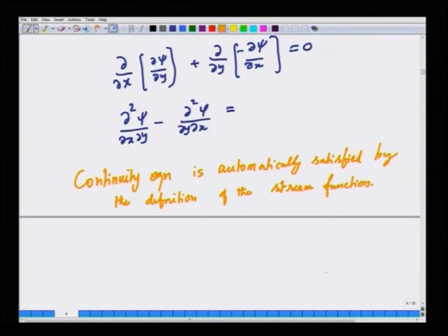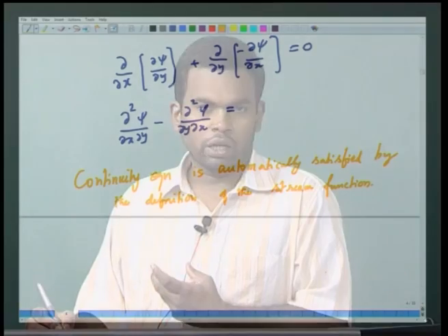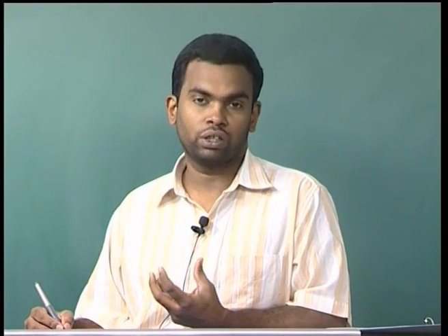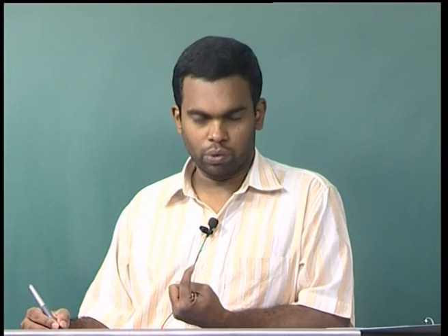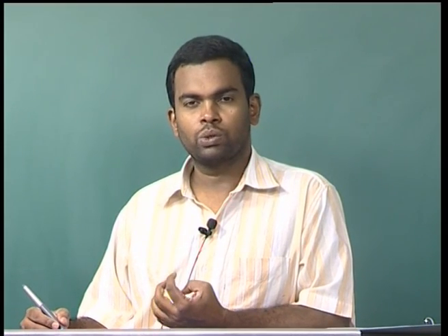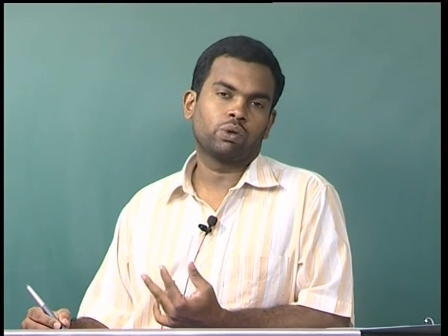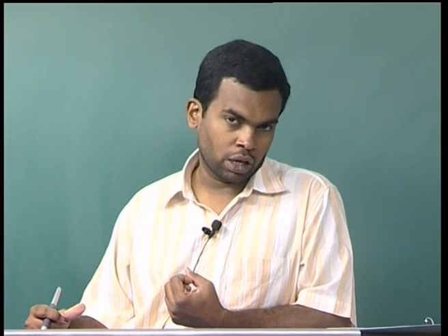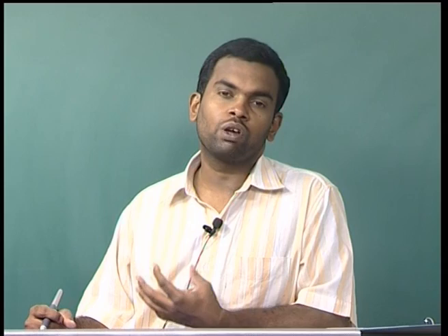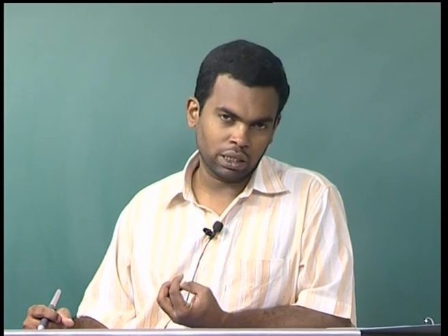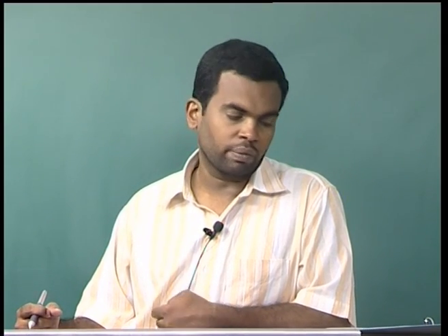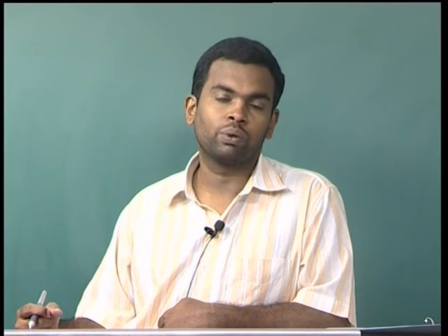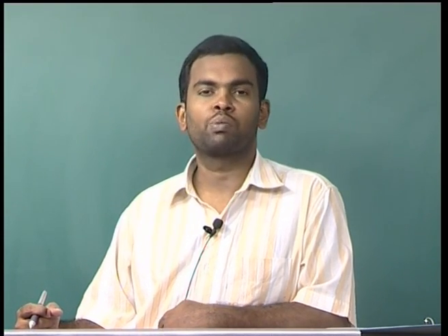So, this is a very important conclusion, because by defining the stream function in this fashion, you are automatically satisfying the continuity equation for 2-dimensional incompressible flows. That is a great simplification, because when you want to proceed further to momentum balance, you will find that you will have two sets of equations, the mass balance and momentum balance, which are coupled to each other. But by defining the stream function, you are doing away with one equation, you have to solve one equation less, and it is always nice to solve a lesser number of equations than more, mathematically speaking. So, in that sense, the stream function is very helpful in the solution of 2-dimensional incompressible flow problems.